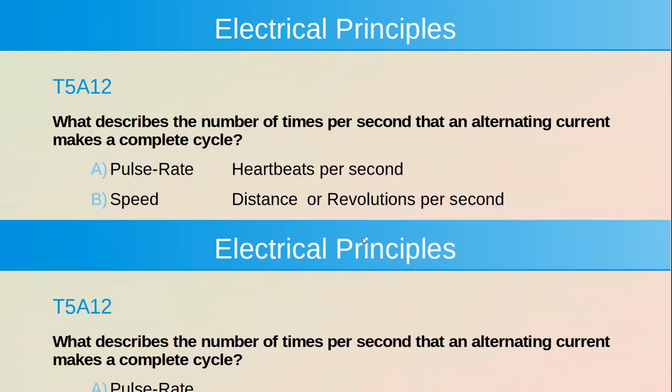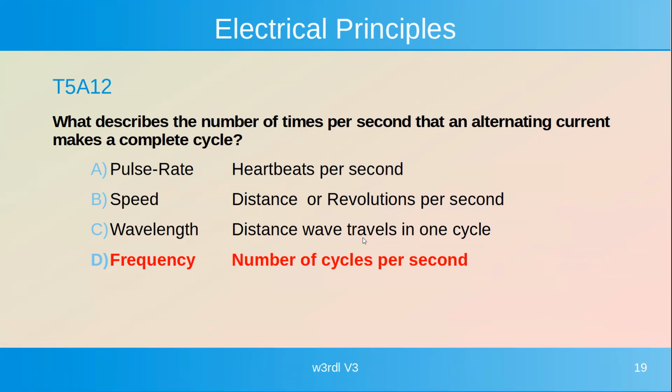So in your house, your wall outlet again, 120 volt AC, right? Anybody know the cycles per second of your wall outlet, 120 volts? 60. Or the hertz? 60 hertz. Right. So there's 60 cycles, so that one sine waveform, 60 of those per second at 120 volts coming out of your wall socket. And it's actually very accurate. It doesn't vary but a fraction of a hertz.